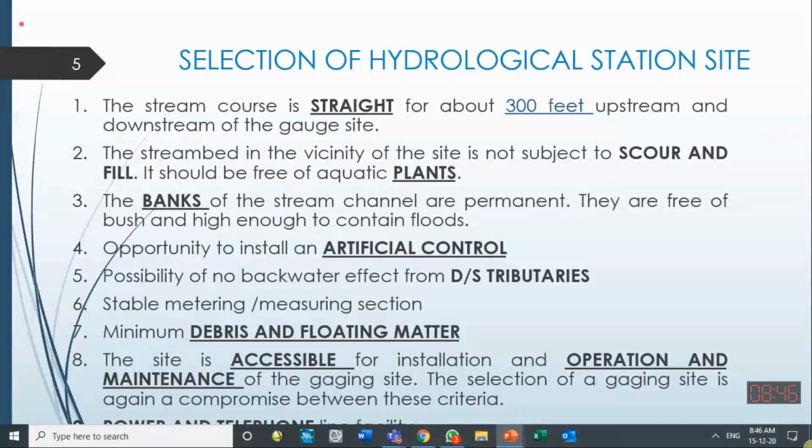But if sedimentation has occurred over there and the bed has risen to 105 meter, then the flood level will also go up. That will change the relationship between discharge and stage. Previously we would expect that a 100,000 cubic flood would come with a water level of 110 meter. Now it will be 115 or more than that.